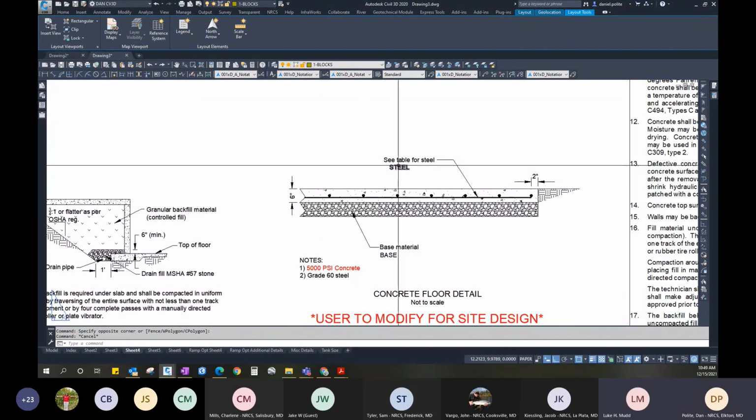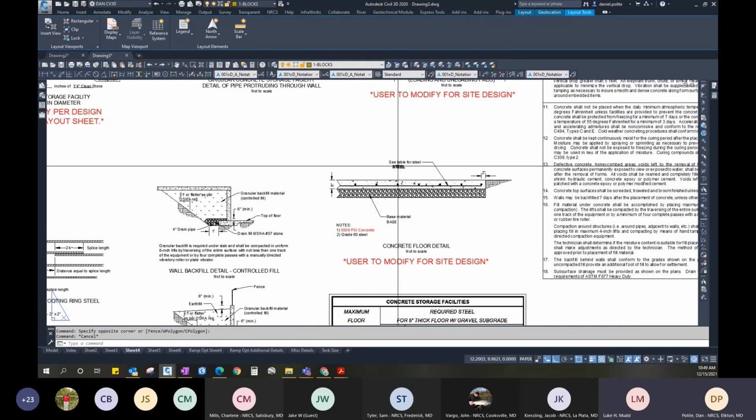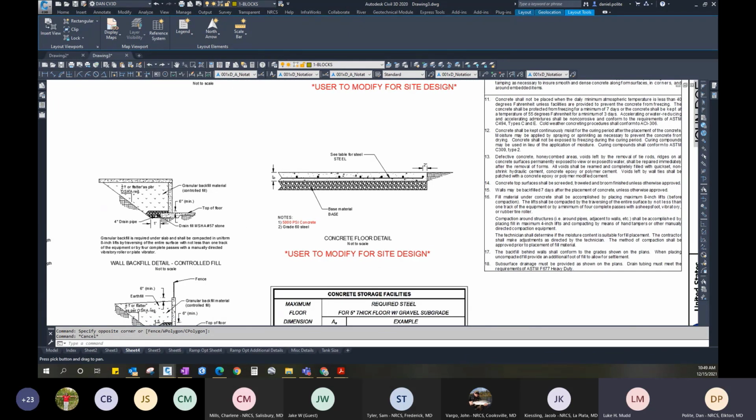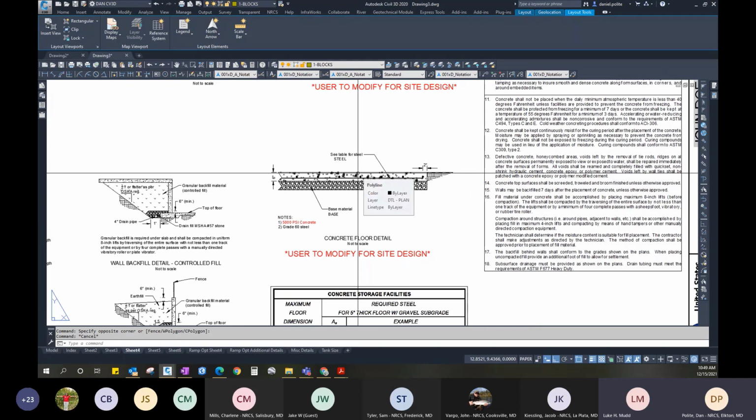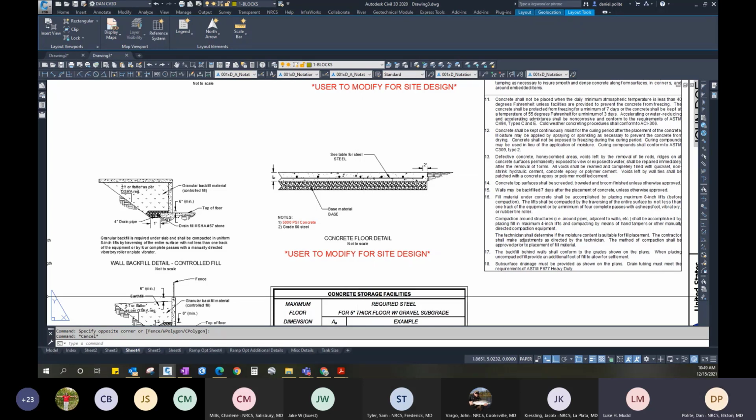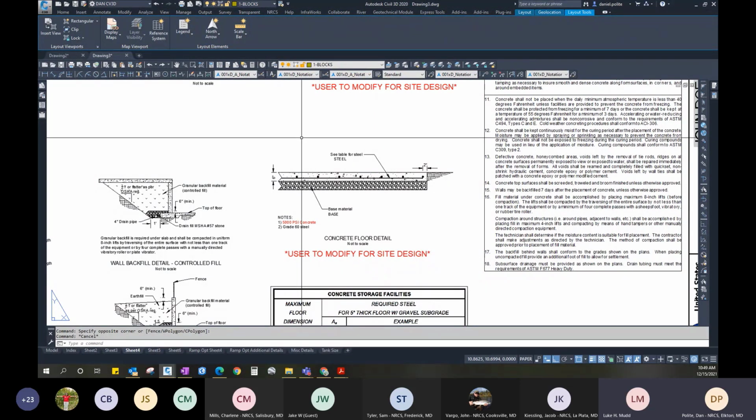The problem is that now I have to recreate that block. In other words, I'm not editing in place; I basically took that block right out of everything. Does that make sense to everybody when you explode it? Because that's a real important one.